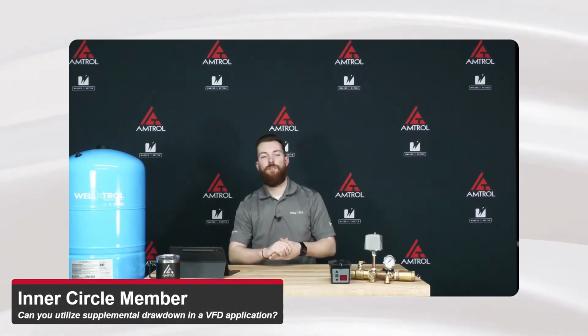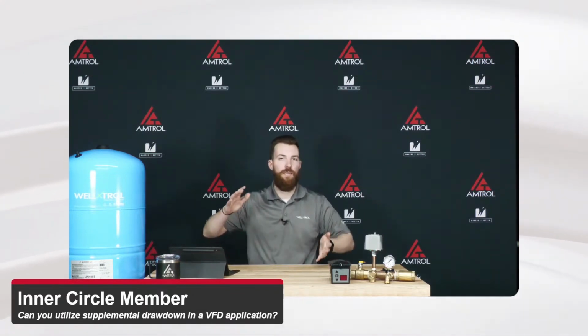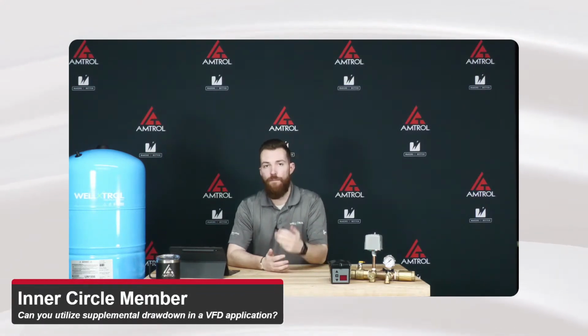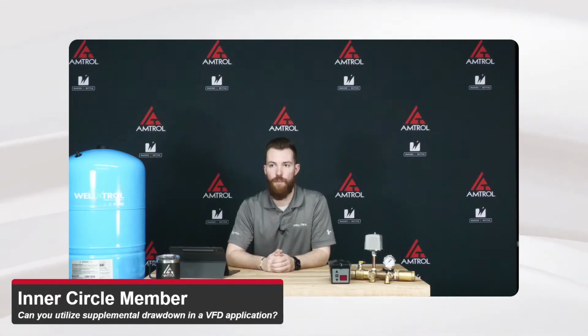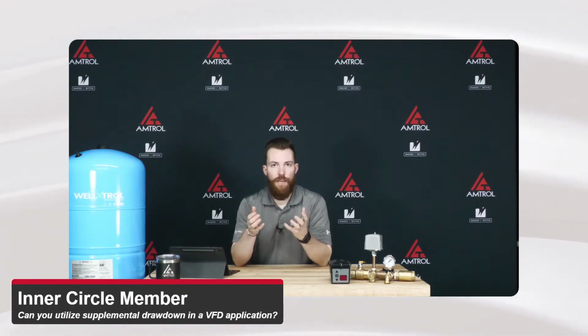Can you utilize supplemental drawdown in a VFD application? Okay, yeah, so for supplemental drawdown on VFDs, absolutely. I'm surprised I didn't mention it. VFDs are a very common instance where we'd use supplemental drawdown because you're not using a nice wide pressure range like you would on a traditional well setup. I've spoken at customer conferences with pump manufacturers that build pre-built skids, so they have their pumps with a pressure vessel and they ship that out to a customer, and they'll use our vessels on there. And that's exactly what they're doing, sizing for supplemental drawdown.